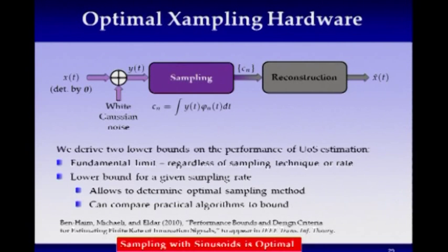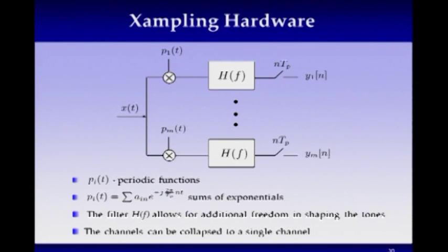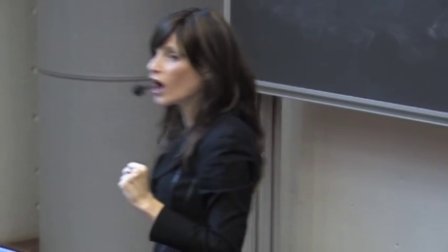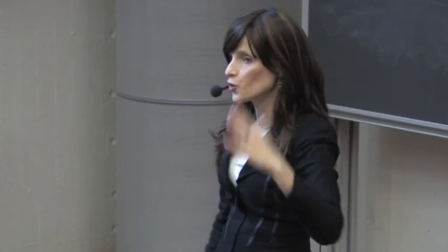That's almost true. The problem is that if you actually just applied those results, you would need many, many sinusoids. If you think about the multiband problem, suppose we have 12 bands, we would need, let's say, 24 sinusoids. That starts to become hard to do in hardware. Trying to get 24 VCOs on a piece of hardware, they have to be completely synchronized. It starts becoming a little bit tricky. We've tried to do that, and you could do that up to 8 or 10, but beyond that, you already have hardware issues.